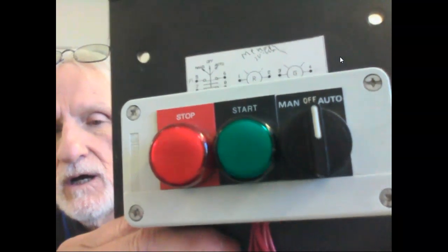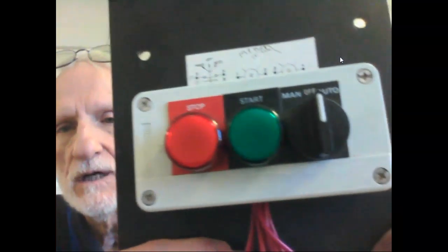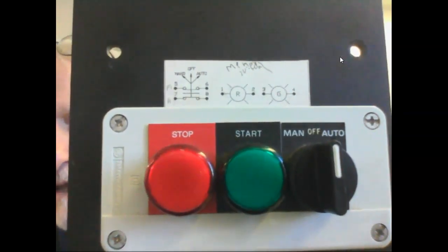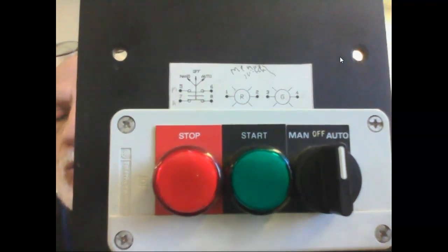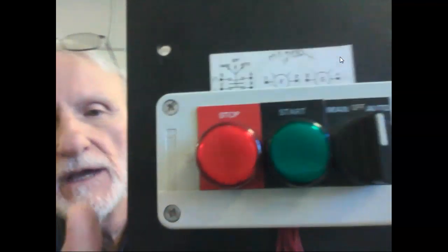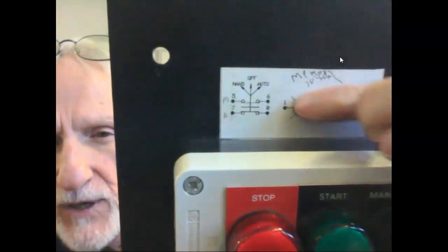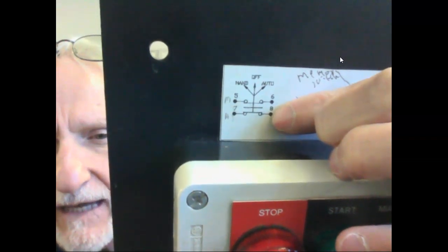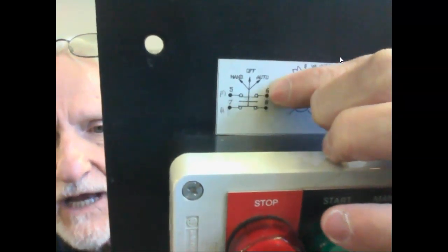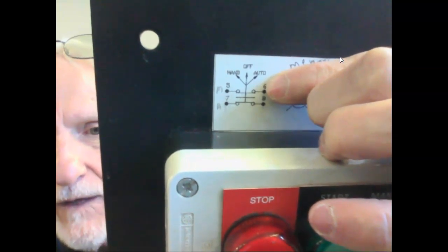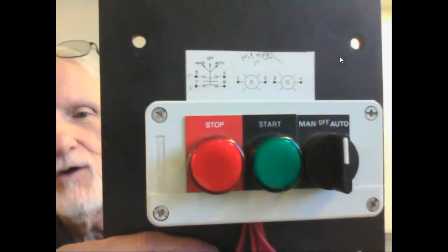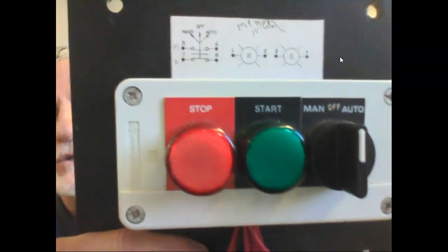So this is our selector switch here. It's a 3-position with a center off. So right now it's in the off position. And then they called it auto and manual, but if I put it in manual, then here's our diagram. If I put it in manual, then the bottom contact will close between 7 and 8. If y'all can see it better. Between 7 and 8. And then if I put it in auto, then the contacts between 5 and 6 would close. If I put it in off position, then neither set of contacts are closed. So even though they're labeled auto and manual, you use the contacts.